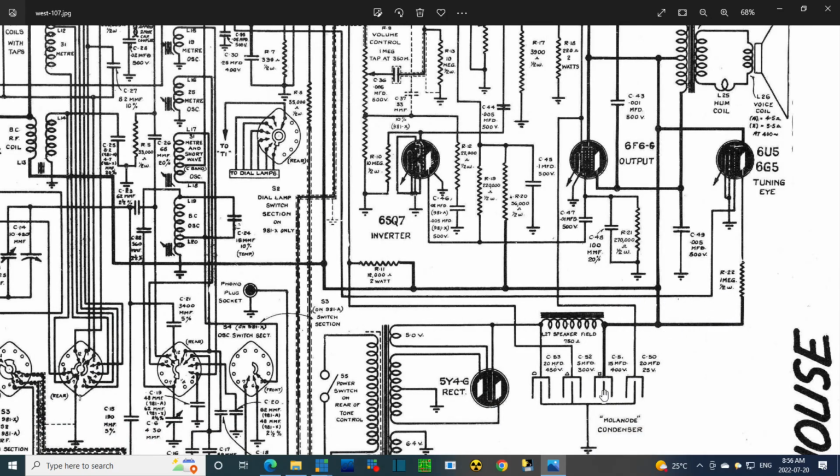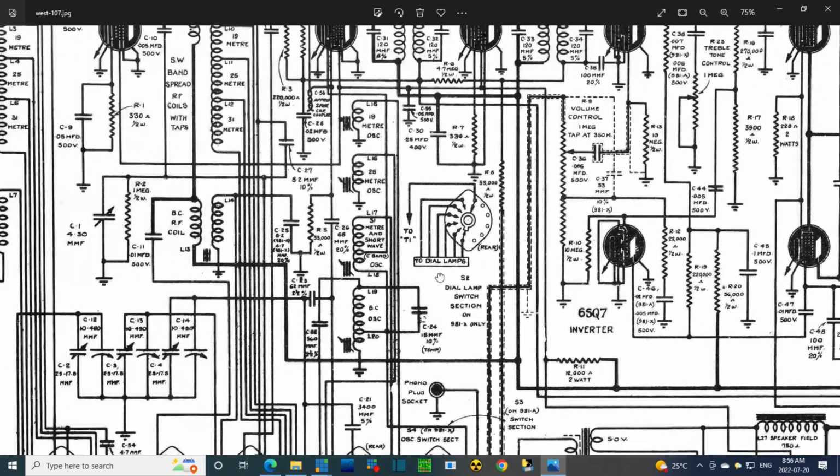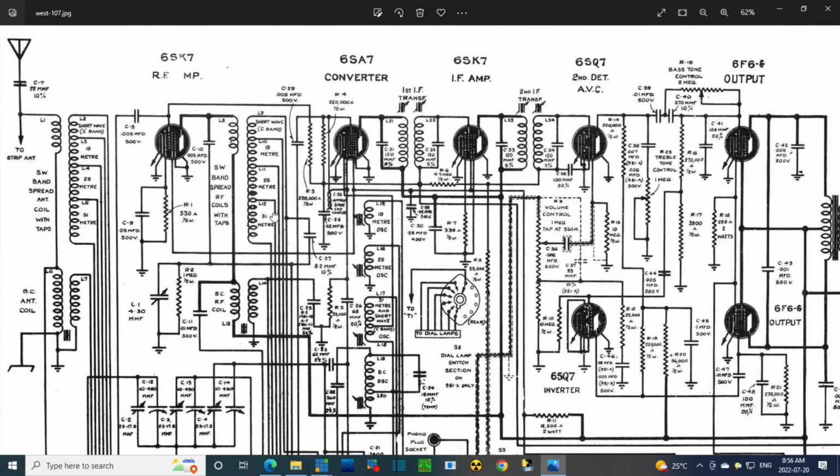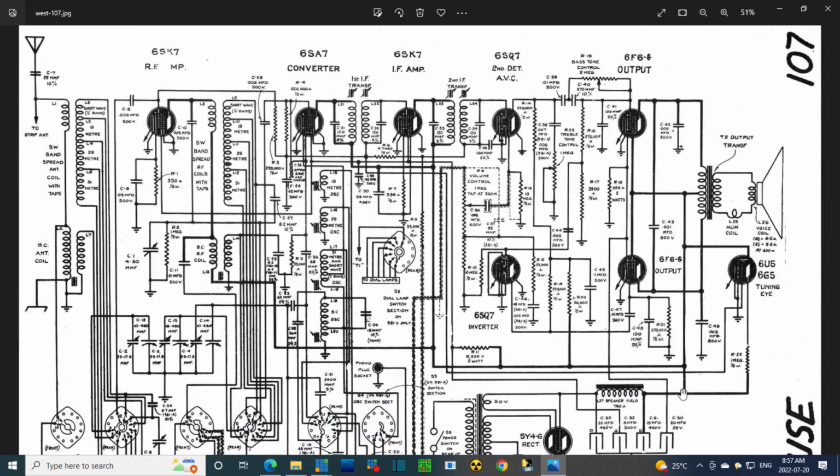You see it come all the way down to the power supply here. 400 volts. Now, that's pretty high. It wouldn't be 400 at the tubes necessarily, but that's a pretty high voltage in this radio. There's no voltage statement here as to what the voltage is on this line, except that 400. That's a rating, I think. That's probably a rating for the capacitor, so we could guess 300 volts here. Probably a good guess. So the guy's got 300 volts on him.